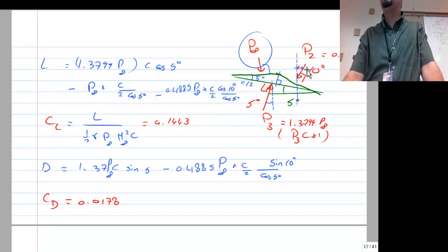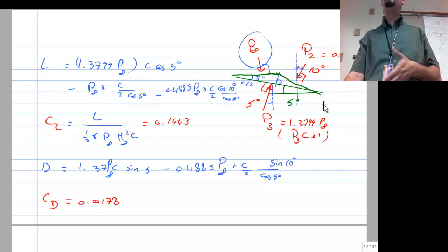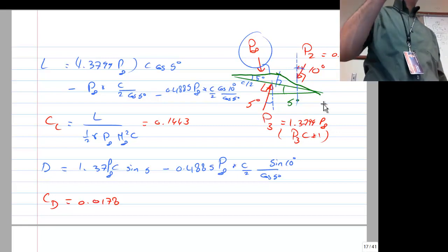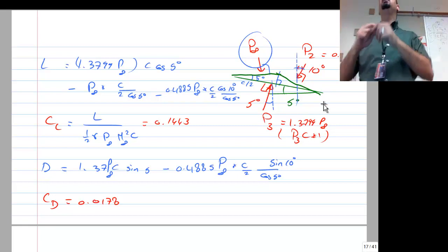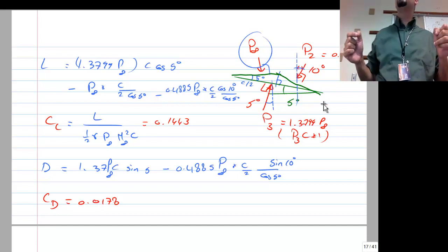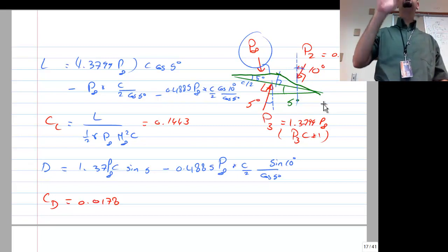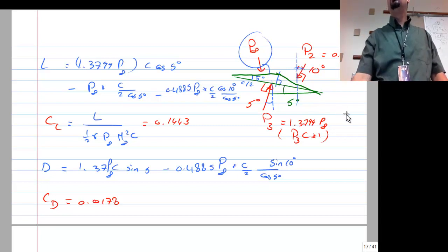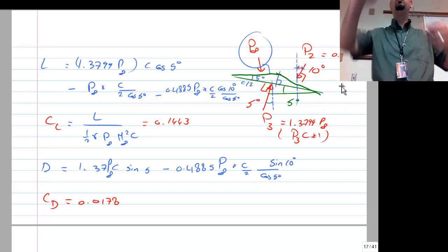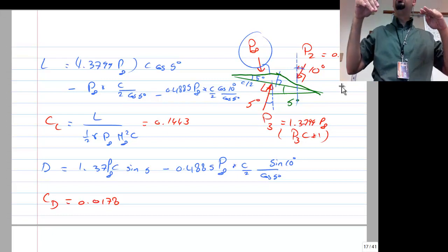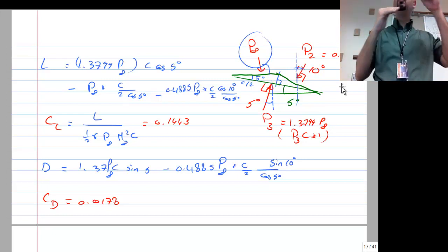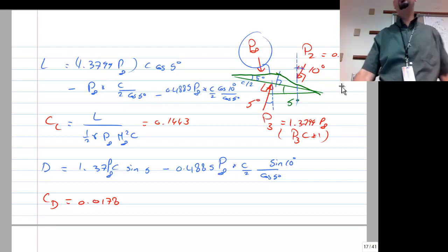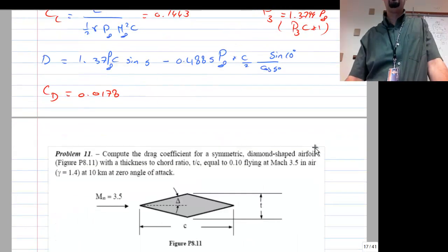So for example, when you try to calculate the force from pressure, first you split it and then you multiply by the area. A shortcut is to say the vertical component would be the whole pressure times the projected area. That would be equivalent to getting the full pressure, splitting it into components, and multiplying by the true lengths. When you do this, it's exactly the same as not splitting the pressure into vertical and horizontal components, and not even multiplying by the true lengths, because sometimes the length is hard to get. Let's just multiply the pressure times the projected area. So if you want to get the vertical component of the pressure force on that surface, you multiply the whole pressure times the projected component of the area in the vertical direction. Whatever makes it easier for you, use it, all right?